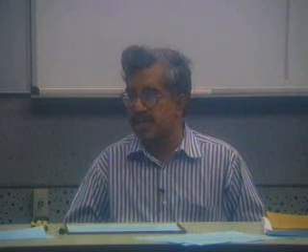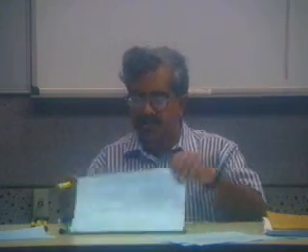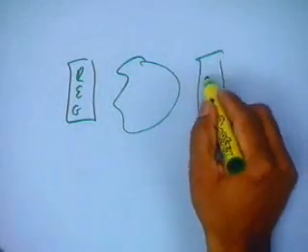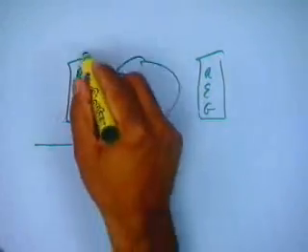In-speed is full speed. Let us say the circuit is to work at 20 megahertz, for example. Then you can actually perform testing working with the circuit at 20 megahertz. So, you are not going to slow down. If you are feeding in the test pattern, there is a time that is required to feed it in. You will feed in a test pattern, typically serially shift the test pattern in. Remember we said there is a register here, there is some logic here, there is a register here, and there is the scan path.